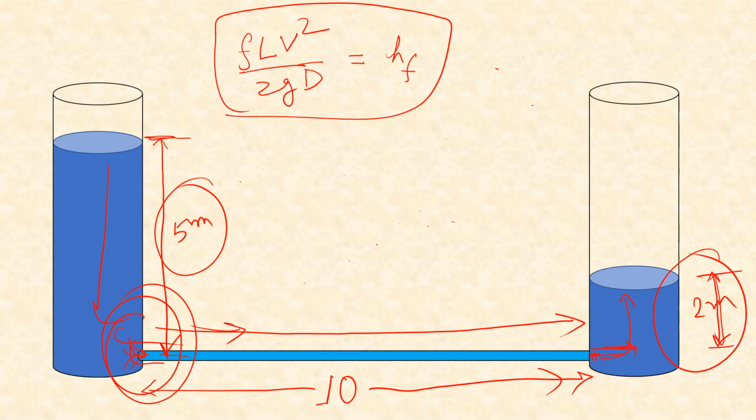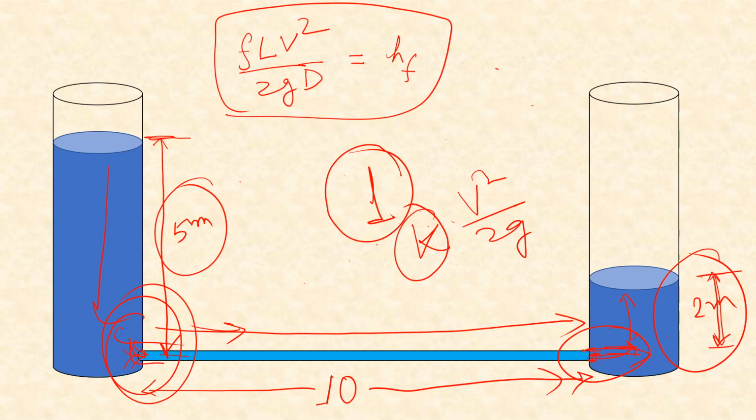One thing here, this velocity head loss or the loss at exit is equal to v square by 2g, and there will be no coefficient multiplied with it, and that's because no matter what kind of arrangement you make at this point, either it is smooth transition or abrupt transition, whatever was the velocity will always be lost. We can never recover them, and that's why this value of K is always equal to 1.